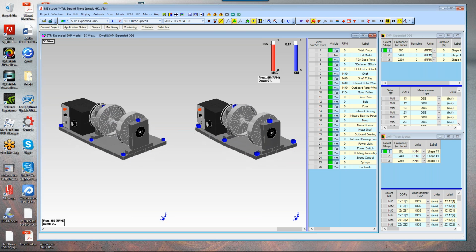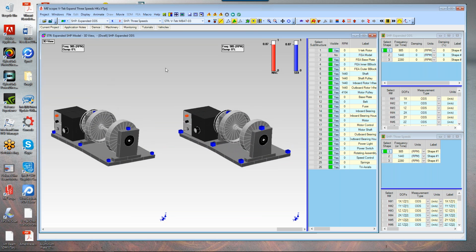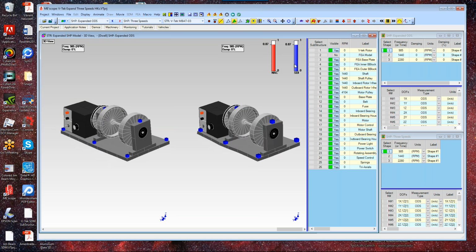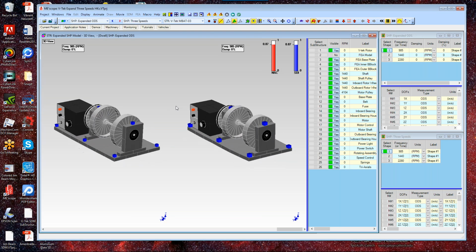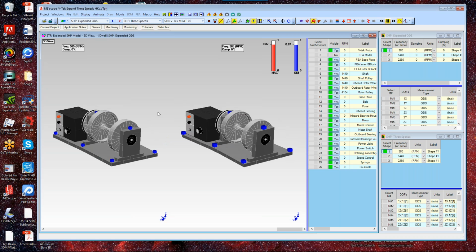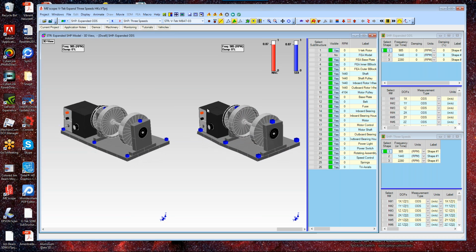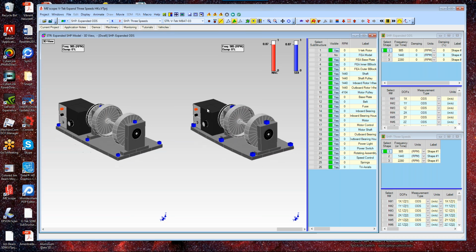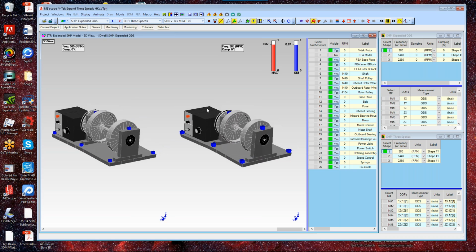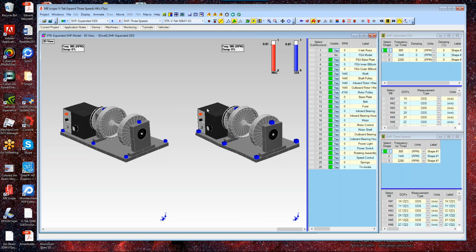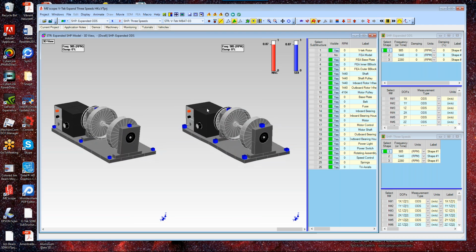What we're looking at up here are the MAC values. Let me put these up. The MAC value and the SDI value of these two shapes. On the left is the expanded shape. On the right is the experimental data, the ODS that was taken off of the running speed of the machine, simply saving the peak values from the 24 spectra.